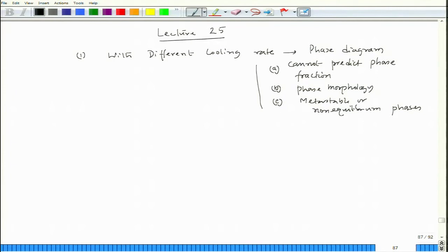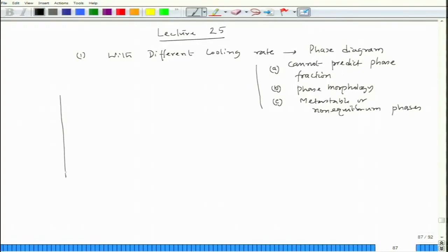Now, since we have talked about steel and the microstructure of hypoeutectoid steel, let us get into the microstructure of pearlitic compositions as well as hypereutectoid compositions. The pearlitic composition, because if I draw the steel phase diagram, this is 2% carbon and this is 0% carbon.